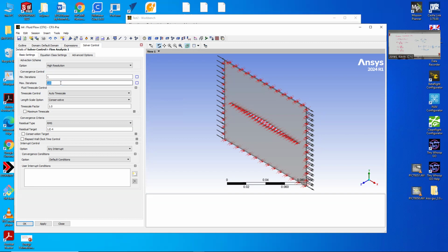So what I like to do usually is go ahead and run a bunch of stuff up front to get me headed in the right direction. And then we'll come back and add the mesh refinement afterwards. Again, let's make this something unobtainable. Actually, I think it can get to 10e minus 9. Since we're laminar and supersonic, it actually converges incredibly well. Let's see, I think that's it in here. So we should be able to just save it. Go. I didn't forget anything.